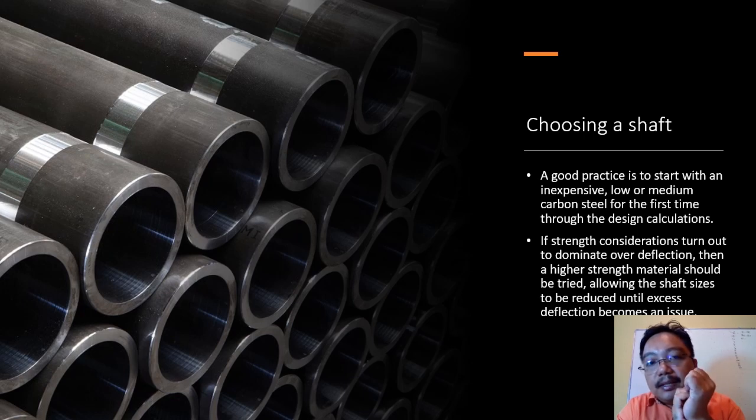If the shaft cannot support the load, upgrade to higher strength until you get the shaft that can support the load, and you add the safety factor, times 1.0, times 1.2, 1.3, and then you get the result, and then you choose that shaft. Okay.